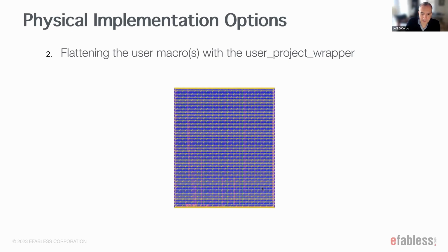Because the logic's been flattened and implemented at the top level, any additional space is filled with either decap or fill cells to consume the entire area. So there's a lot more detail, your file size gets a lot larger, and when you're running any kind of verification or timing steps, they're going to take a lot longer to complete as well.